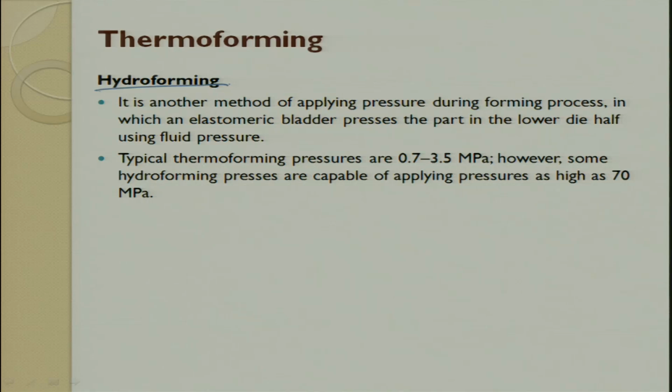One of the tricks is using hydroforming. What is hydroforming? You apply water at a very high pressure, so that you consolidate to get the required output. When you push water, you have to put it inside an elastomeric bladder. So, the pressure is applied rather than using a metal. Here the pressure is applied through hydroforming, in which we take an elastomer, fill it with water or any fluid at high pressure, and then try to get a consolidation.